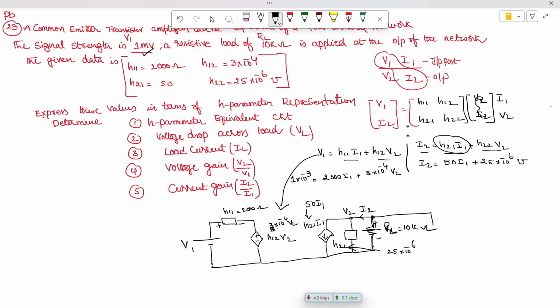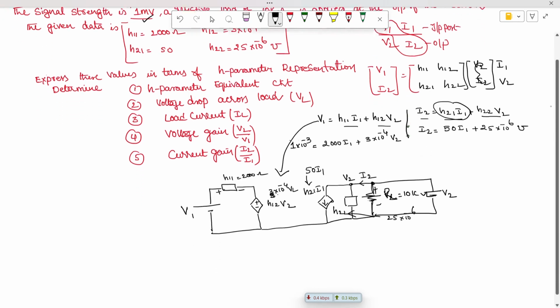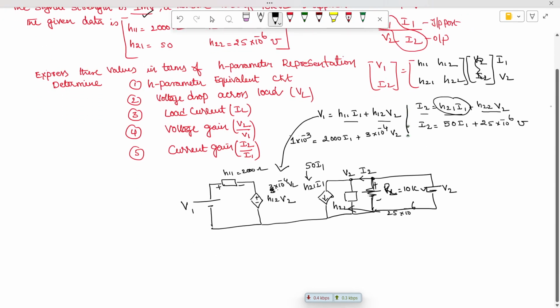Automatically we have already excited with a voltage of V2, and the current is flowing in this direction. So generally if the current flows in this direction, we know how to write down the current I2. This is flowing towards, but actually current will flow down. We know that I2 is equal to, what is the voltage at this point? The voltage at this point is V2 here. The voltage at this point is also V2 here. So the current flowing in this branch is nothing but I2. I am assuming I2 is equal to V2 minus 0 divided by R.